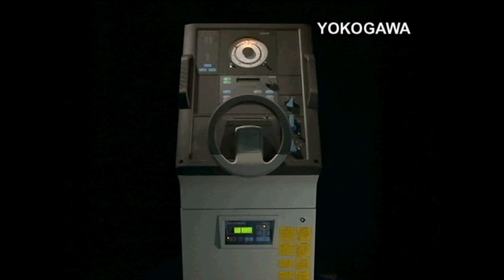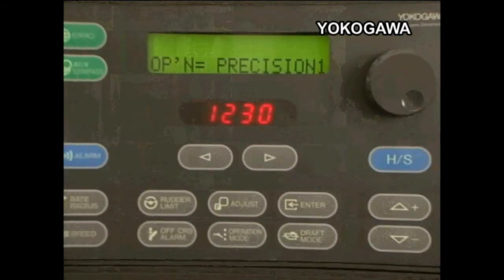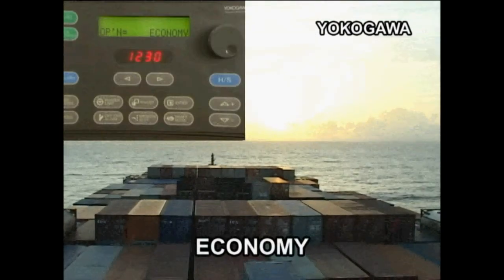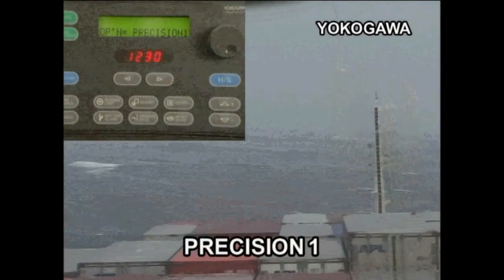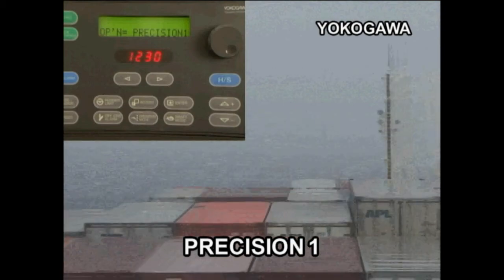Now let's look at Yokogawa's steering system. It has three operational modes: Economy, Precision 1 and Precision 2. Economy is an automatic steering mode designed for energy conservation during cross-ocean voyages. When underway in a rough sea and experiencing excessive yawing, it's better to use Precision 1 instead of Economy mode.